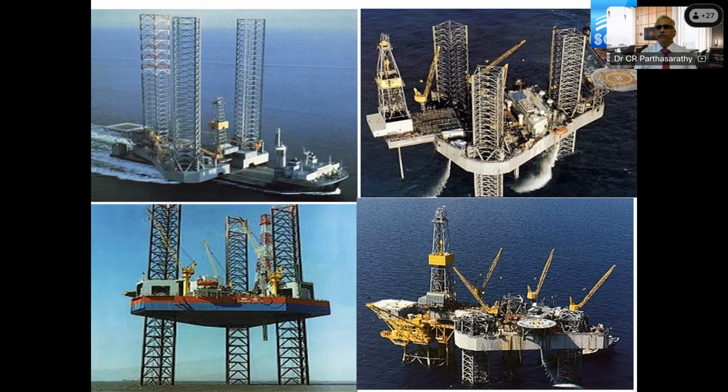So when does the leg stop? How deep will the leg penetrate? The leg will stop where the ultimate bearing capacity of the soil exceeds the allowable applied load on the legs.